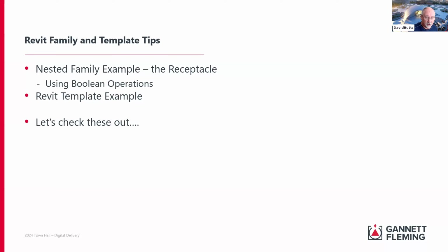You can have all the blocks you want in your template, but don't have a physical representation off to the side that somebody picks, copies, and puts into a plan view or somewhere else in the view. Have the blocks in there, but don't have them placed, because you're changing the extents of the drawing and putting in data that's not relevant to the design. The only thing that should ever go in a Revit model, and the only thing that should ever go in an AutoCAD drawing, is what you're actually creating: that representation of that object, those lines that represent a wall. That's just a rule of thumb after almost 4 decades of doing this. You definitely want to make sure you're doing that.